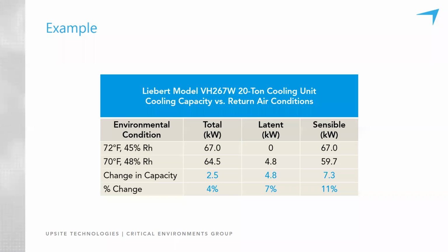Latent heat or latent cooling, as it's sometimes referred to. So we want to remove the latent cooling. We want to remove the condensation on the coils. And when we do that, by just raising the supply temperature, in this case 2 degrees, the relative humidity drops to 45%.